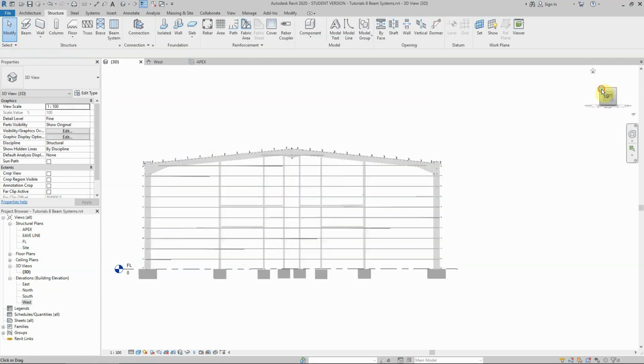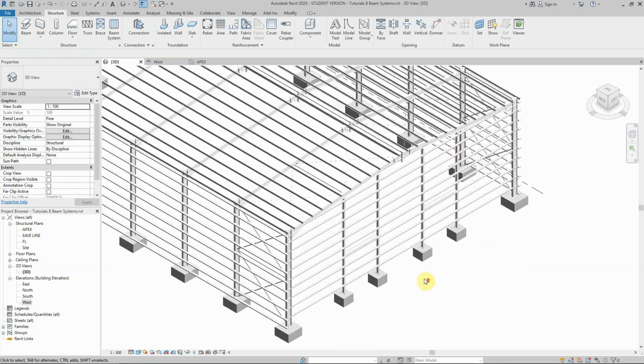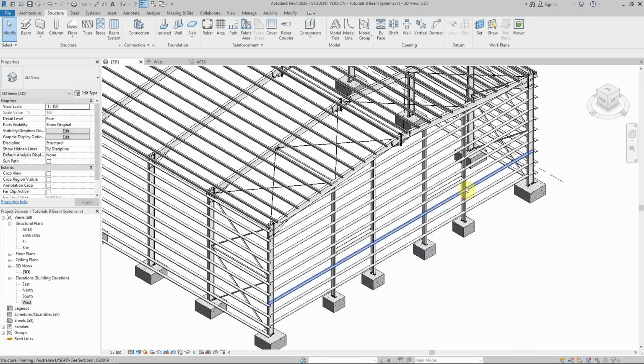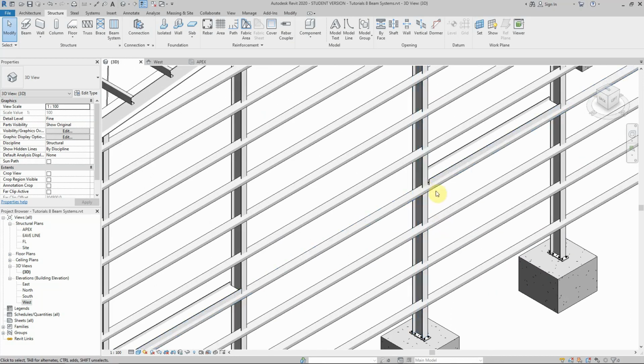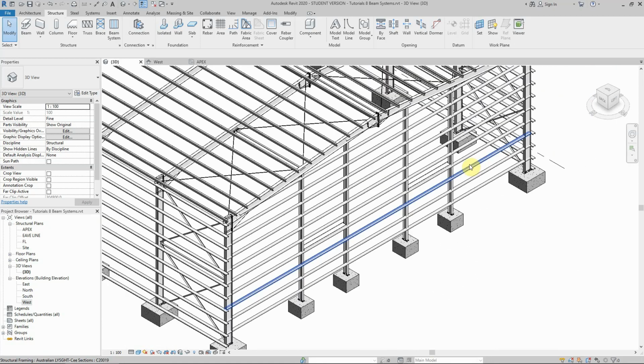Or a mistake, or not a big problem, but something has to be changed. To start with, our girts are blocking the openings. So that shouldn't go there. Secondly, we have to readjust the location of these girts properly. That's fine, we can do it, it shouldn't be a problem. But the first thing, we have to clear these openings. I've got these two smaller openings here, the 4 meters by 4 meters doors.